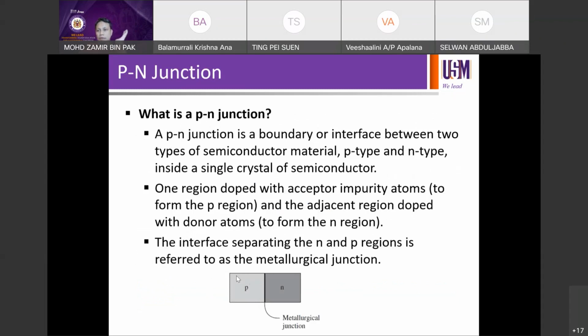It's not happening across the P, it's not happening across the N, but you're going to have diffusion from the region near the junction, because this is the region where you see the gradient. If you are away from the junction, going further into P or further into N, the carriers won't be able to see the concentration gradient, because in front of them there is still the same level of holes or the same level of electrons. So it just doesn't see the gradient yet. The place where they're going to see the gradient is close to the junction.